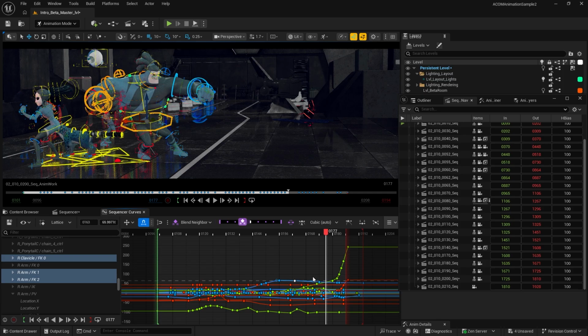I'm not manipulating the keyframe's position, but instead I'm just playing with the slider. If you press Shift U, you can switch from one tween tool to another easily. And if you press Ctrl U, that will activate the overshoot, which allows you to extend the available range over 100% if you'd like to exaggerate the movements.